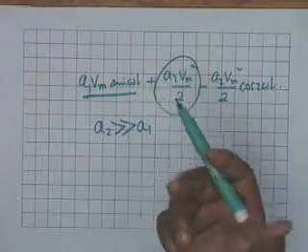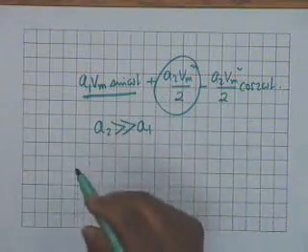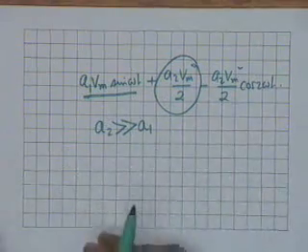Yes. So in this case, when you are talking about amplification, we are getting an A1 Vm term if A1 is greater than 1, but this is the current in the circuit and not the voltage. Whereas what we have applied is the voltage. That's right. So you drop it across the resistance. You pass this current through a resistor and get the voltage. The voltage can be greater than the input voltage. You are quite right. A1 Vm sin omega t is not a voltage, it is a current. So all you have to do is pass it through a 1 ohm resistor, then this current will be converted to a voltage. Alright?